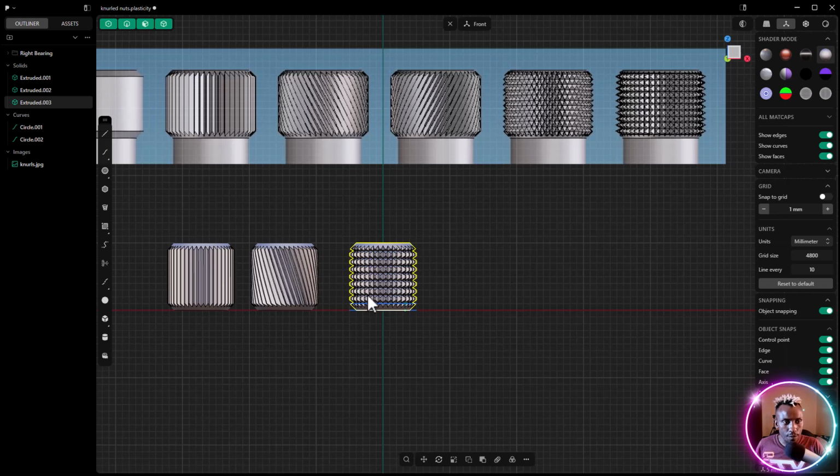Now, what we've done now is vertical and horizontal knurling. As you can see, this one here is a combination of this and this. You first cut your solid with a slant going in this direction, and then add another slant going in this direction and cut it out to get this triangular pattern, while this is more like a square or rectangle.